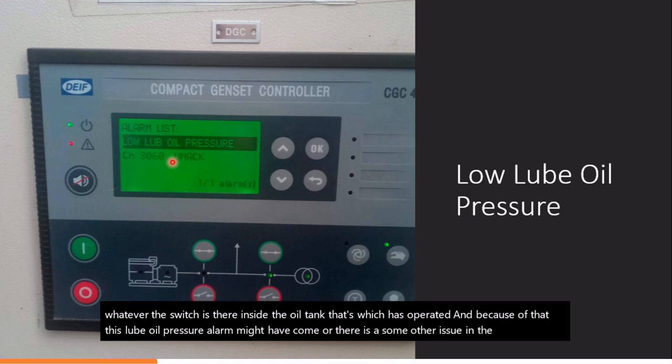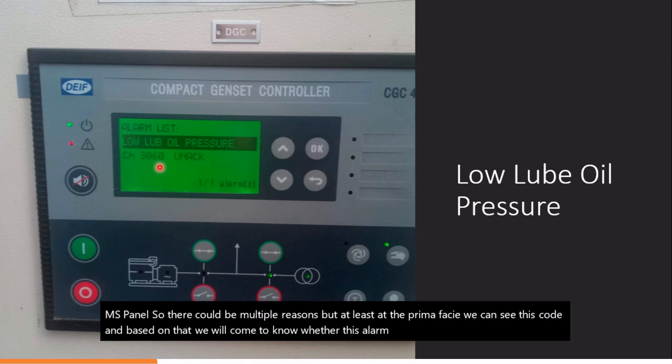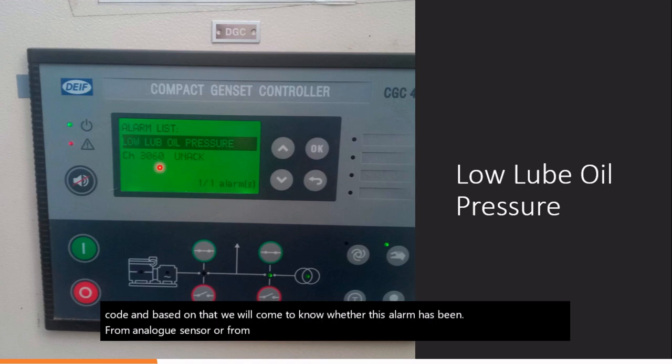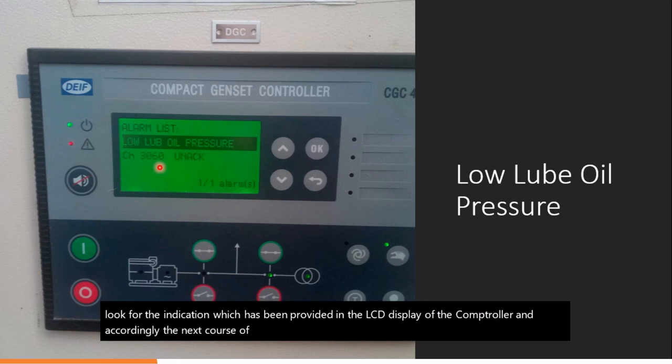So there could be multiple reasons, but at least prima facie we can see this code, and based on that we will come to know whether this alarm is from the analog sensor or from the digital switch. So this is the way the person has to always look for the indication provided on the LCD display of the controller, and accordingly the next course of action has to be taken.